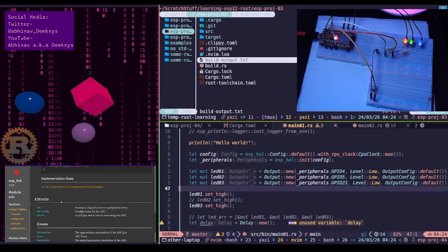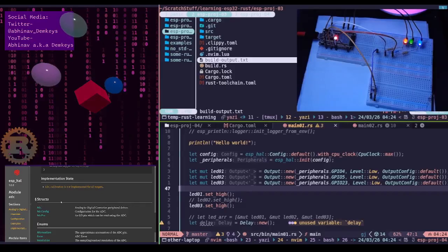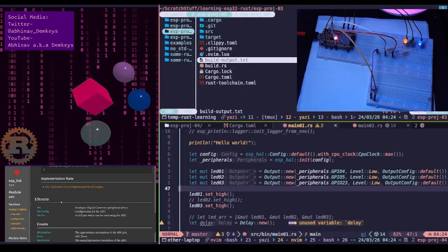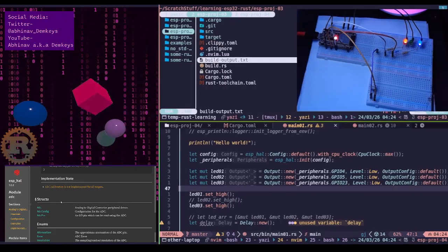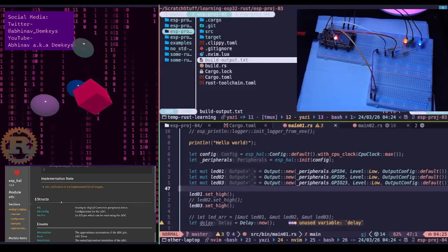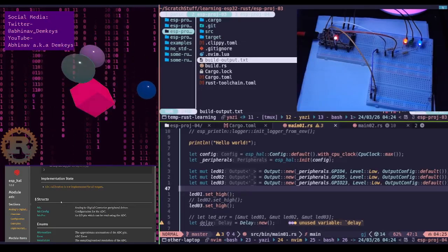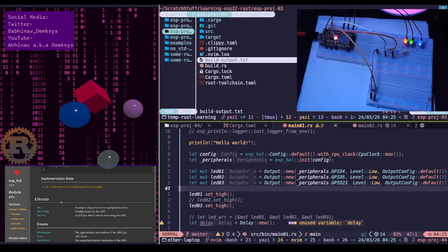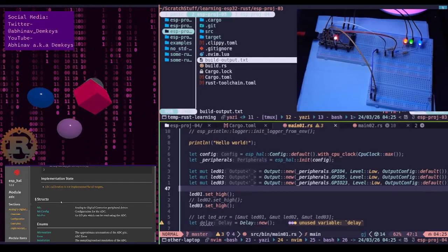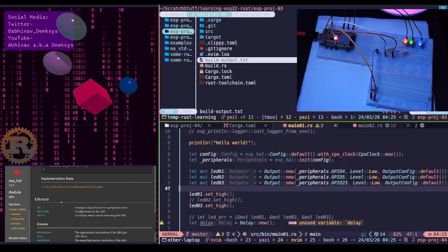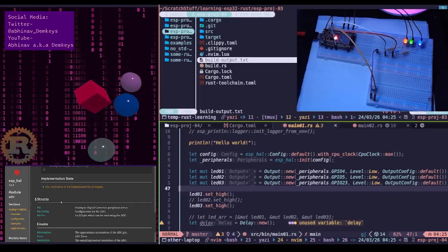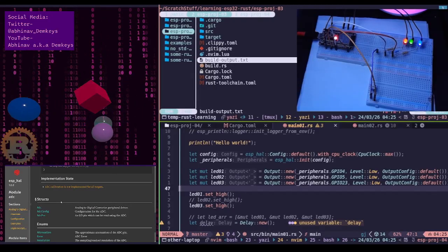In your no STD Rust code, you'll use the ESP32 HAL or ESP HAL to configure so-and-so. The ADC will convert that 0 volt to 3.3 volt range into a number, usually so-and-so. Why the resistor and LED? You mentioned having an LED and a resistor in the mix.